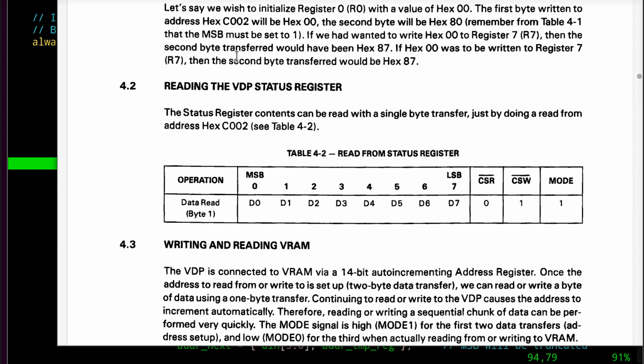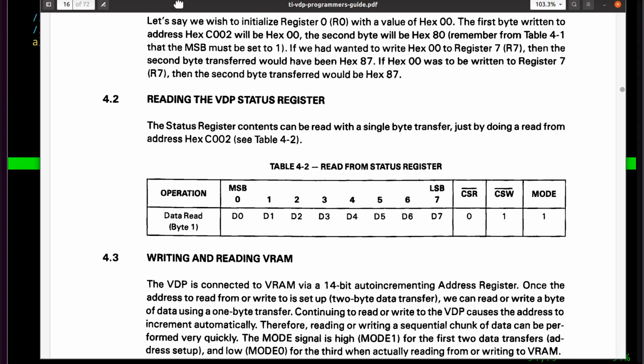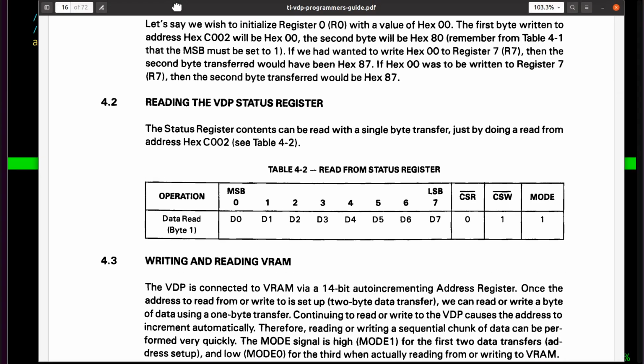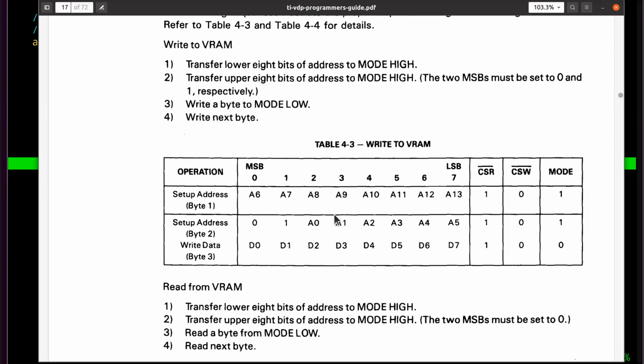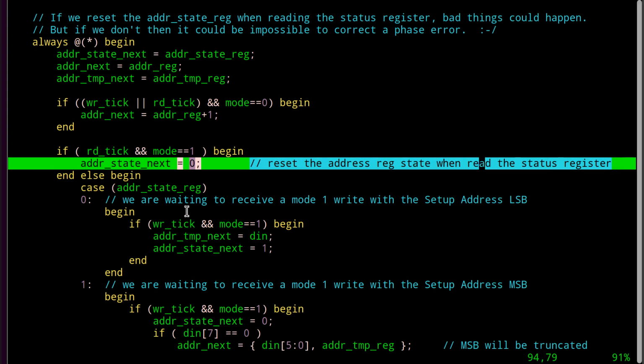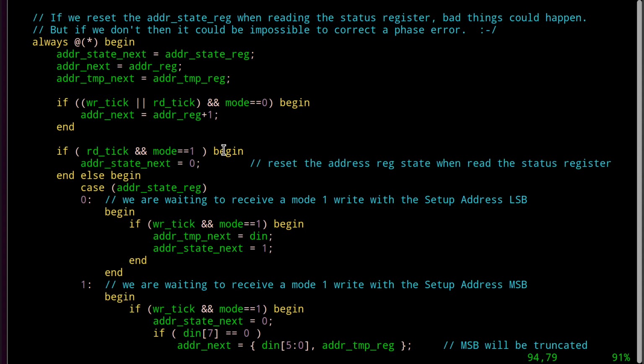The short of it is, you're damned if you do, you're damned if you don't. This thing is a pain in the butt. You need to make real sure that you're not in the middle of doing this while you're getting an interrupt in between here. Otherwise, every time you get an interrupt, you could come back to your program and be broken, okay? So this is annoying, but we need it for compatibility.